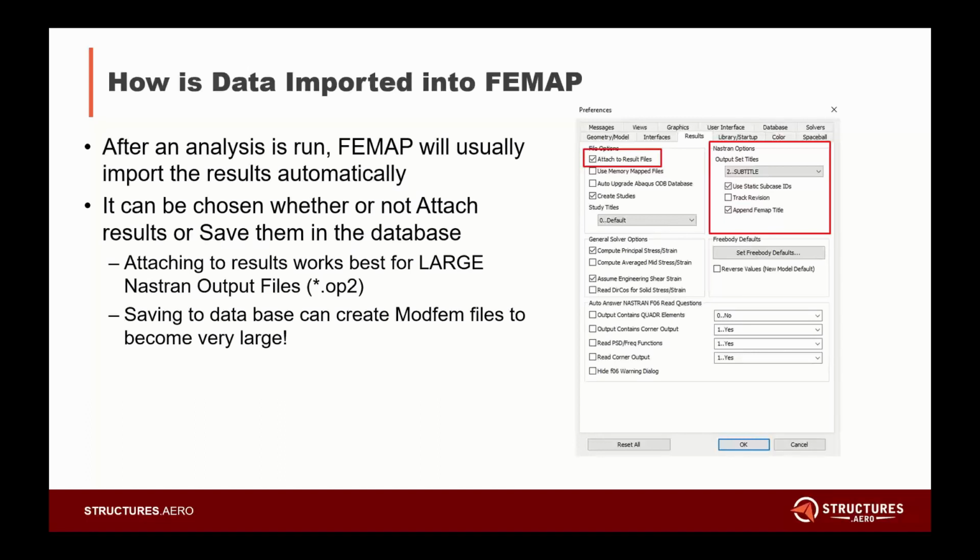When you have a lot of load cases and a lot of output, that becomes super useful. Instead of wondering, well, what was case 1, and having to go back and check, you can just see it in the title while you're post-processing within that output set: oh, this is load case, whatever it's called.